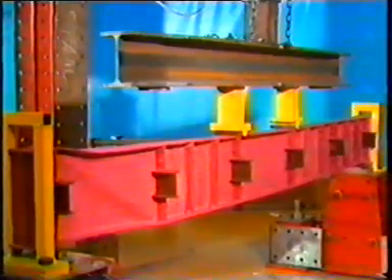Solutions of the plate buckling problem are available for simple, though important, geometrical situations. Here, only a short outline is given of a rectangular plate hinged at the supporting edges, with loads distributed along two edges, including shear stress.